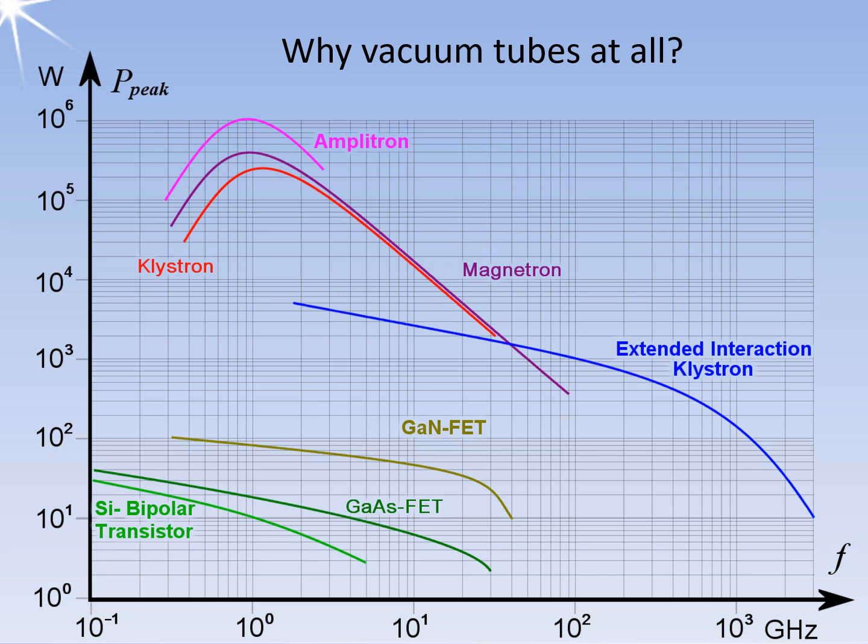While longer pulse durations and intra-pulse modulation can work in most cases, high accuracy is crucial in applications like weather radar. In these situations, transmitting extremely short pulses requires an exceptionally high pulse power of about 500 kilowatts to achieve sufficient radar range. For more cost-effective solutions, non-coherent transmitters often utilize magnetrons. In contrast, transmitters that need precise phase coherence typically use traveling wave tubes or Klystrons.